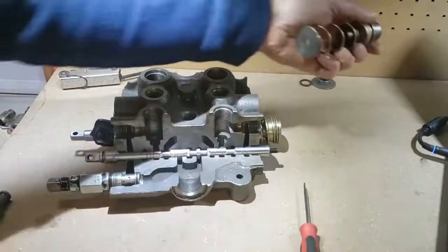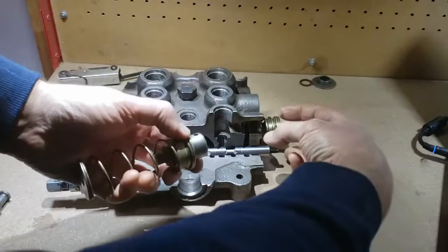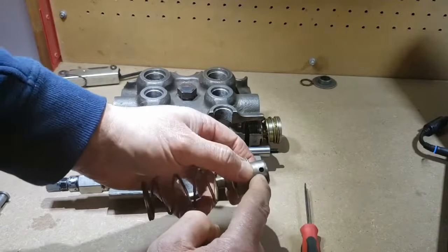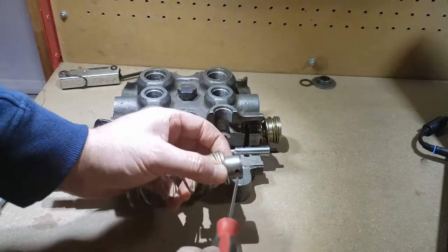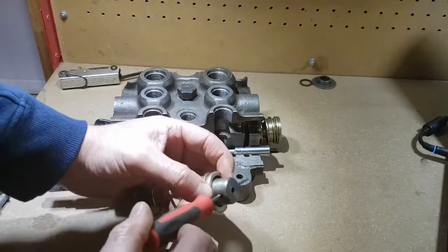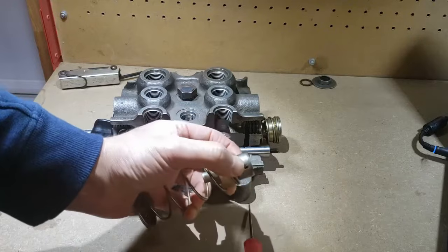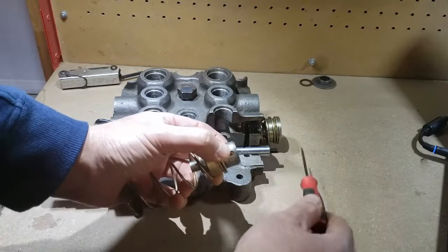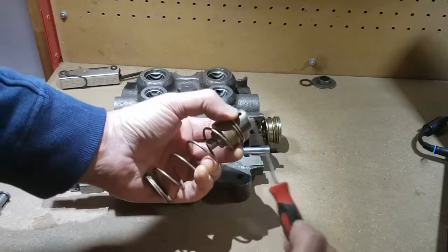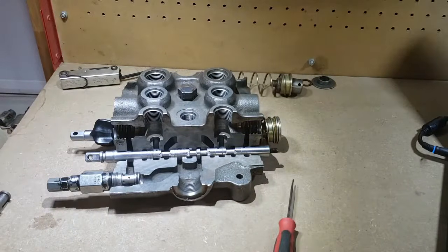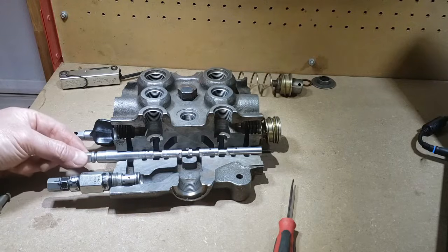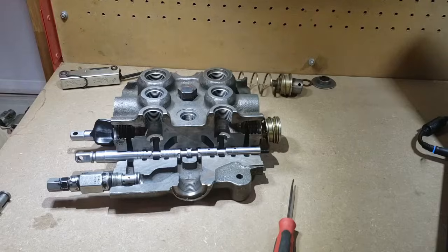And again, I took this assembly apart, but when the cap is on here, the timing would be such there'd be a spring and 2 balls in this cross drilling of this assembly, and those spring-loaded balls would pop out into a detent in the cap that goes on here and latch that spool into the float position, so the operator could then take their foot off of the foot pedal linkage. So that's a 4-position lift spool.